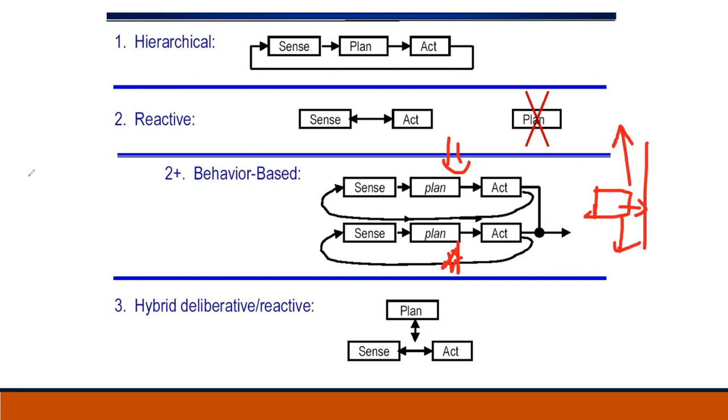But eventually you will have an arbitrator to decide that this time I would like to go right. The arbitrator can be a random number generator, a path optimizer, or some different extra controller. This one is providing more than one plan. So you can combine number one, number two, or several different plans, but use an arbitrator to decide. This is called behavior based. Is that okay?